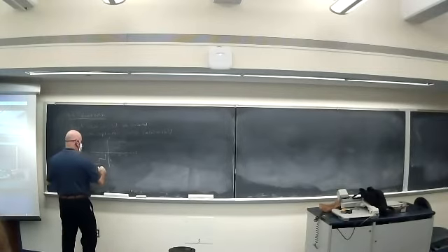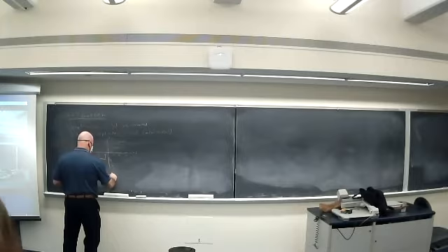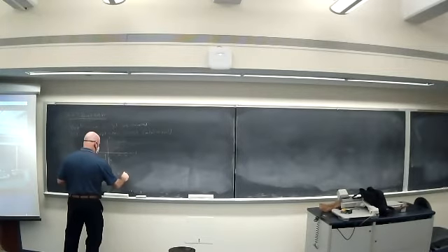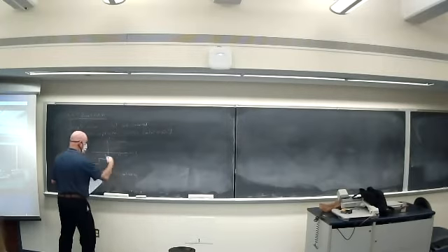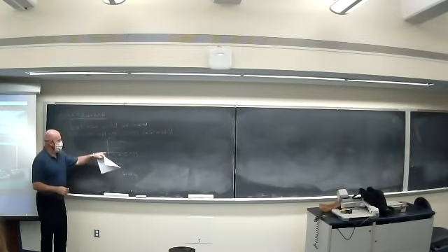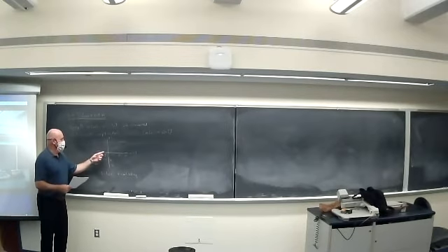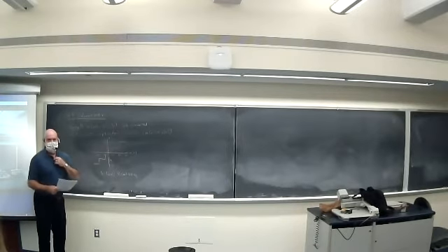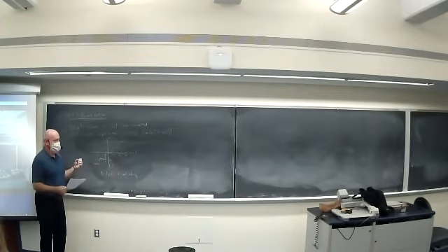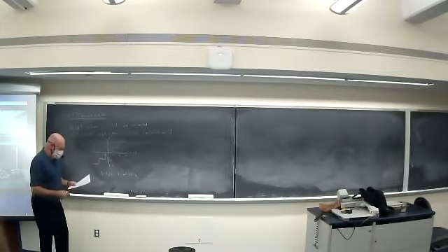So here, as I've drawn it, this would be a 5-level quantizer. It would be designed for any input voltages between -2 and +2. Okay. But any value in that range is converted to one of 5 values. Okay. -2, -1, 0, 1, or 2. And to represent 5 values, we'd actually need 3 bits. Okay. So with 2 bits, we can get 4 things. We need 3 bits to get 5, because with 3 bits, we can go up to 8.